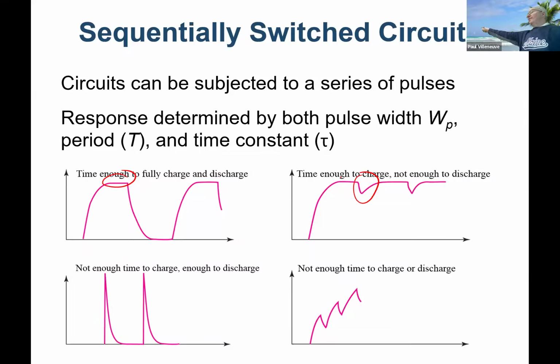At some point that goes away and drops down because it's discharging, but then the sine wave comes back up and starts to charge again. That's how you smooth out your waveform, instead of something that would drop off. So that's where you don't discharge it. You don't give it enough time to discharge, so you basically added a DC. When you say something is not being discharged, you're essentially adding an average value that's a DC value.